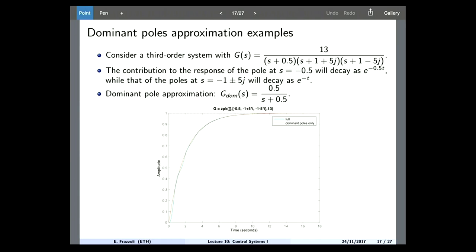We did that several lectures ago, right? You can either do it algebraically. What we did is compute this using the cover-up method, right? Essentially, to compute the residue at one pole, you look at all the distances from all the zeros, take the product, and divide by all the distances from the other poles, okay? That's how we compute the residue. We did that several weeks ago, so maybe go back and review that material, okay?